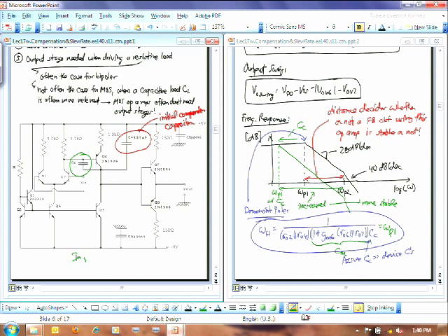And the reason why we want you to do this is because this capacitor should end up being a lot smaller than that one. They're all doing the same function, but instead of putting the capacitor here, if you put it here, you're going to be able to use a much smaller capacitor. And when you have an integrated circuit, that's a huge difference there. Even for the off-chip, that 680 picofarads probably isn't that small a capacitor.